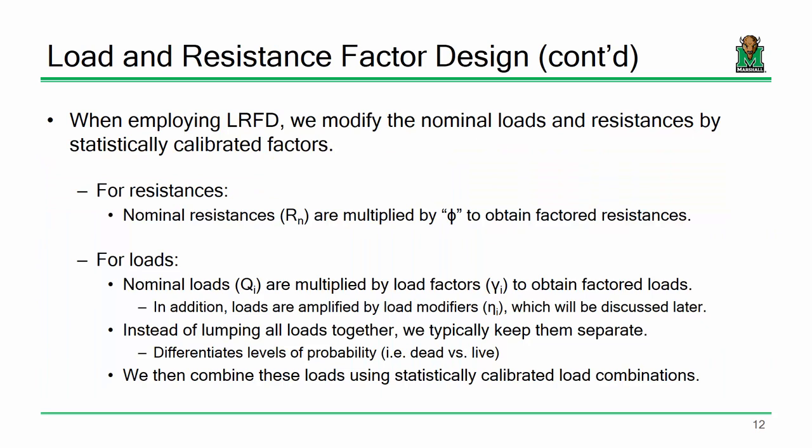All right. So just so everybody's clear on what I mean by LRFD, when we use LRFD, we're not just applying a rote factor of safety to the whole thing. We're factoring both the loads and the resistances. So when we look at resistances, we have this nominal resistance, in other words, the go down to the lab, press on the table, it breaks resistance.